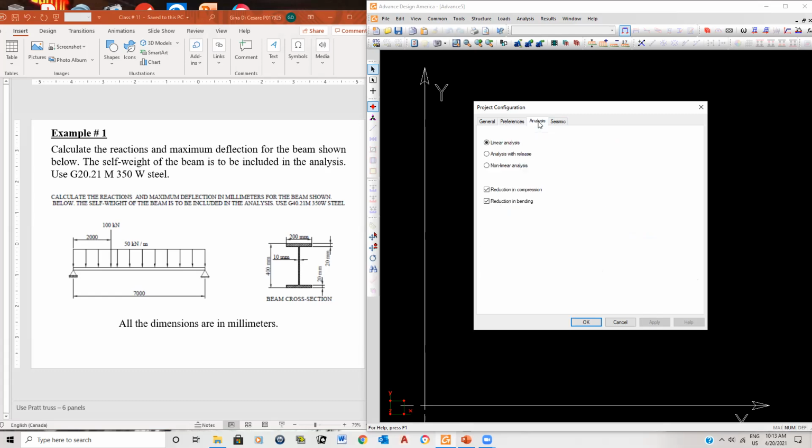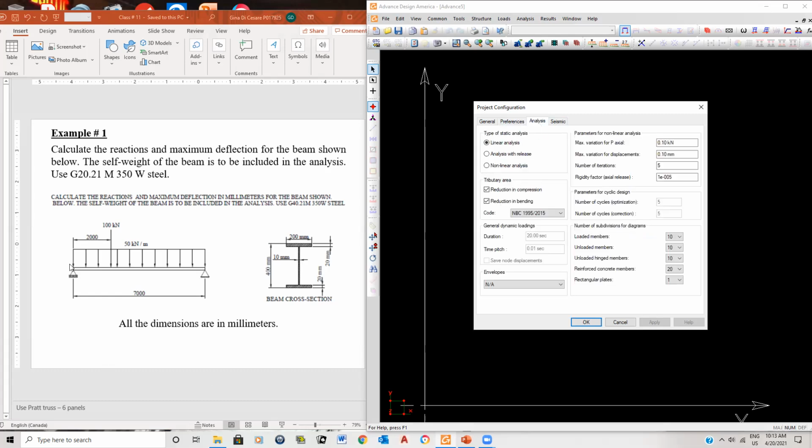And like I said, if ever for whatever reason you find that 10 segments here is not enough because you want to get something a little bit more precise, like I tell you, 10 in practice is more than ample, especially for trusses. You can go for 2 if you only need to know the actual forces. You can go for 5. So if ever you want to have more results, you just increase the values here.